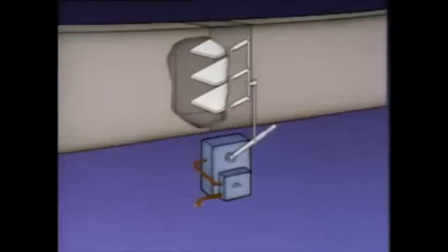In addition to valves, there are many other types of final control elements. Two of the most common are dampers and motors. Dampers, which are often called louvers, use a number of adjustable parallel vanes or blades to control the flow of air and other gases. In some systems, dampers have a pneumatic actuator with a positioner that controls the position of